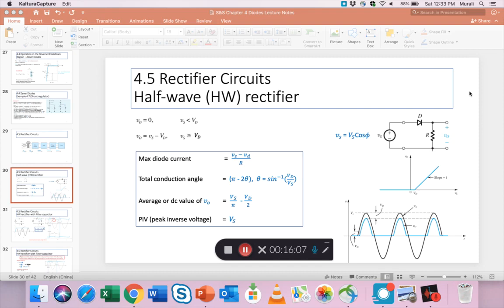Vd is generally the diode voltage, that means the diode on voltage. So when the diode begins to conduct, its voltage across it is roughly constant, although we know it's not exactly constant. It depends on the value of the current, but roughly speaking, we think Vd is a constant of about 0.7 or 0.6 volts.